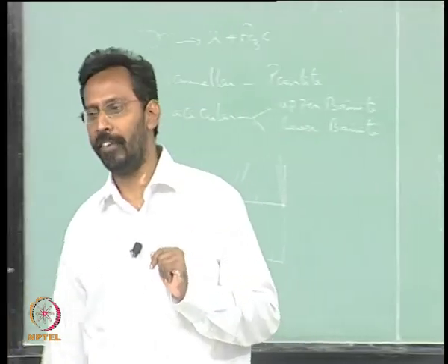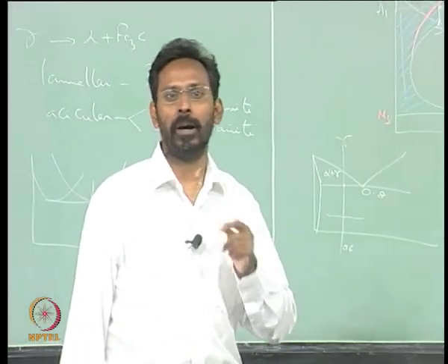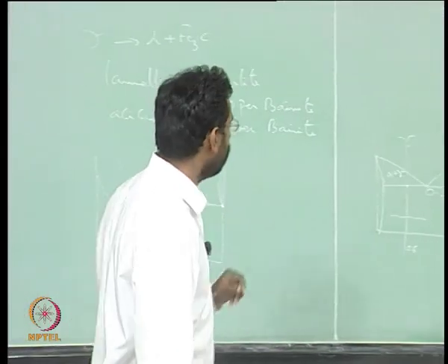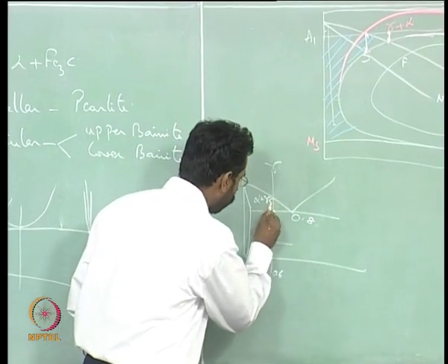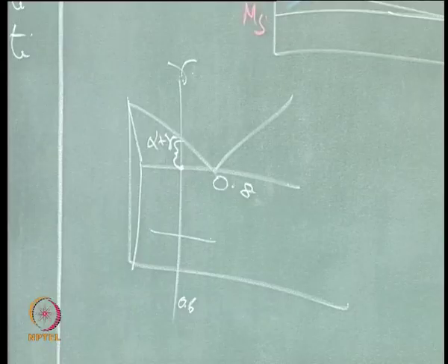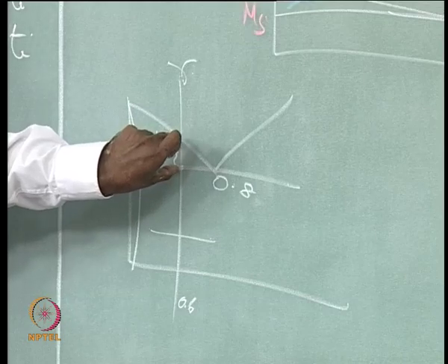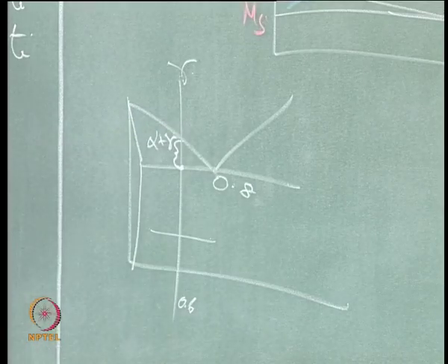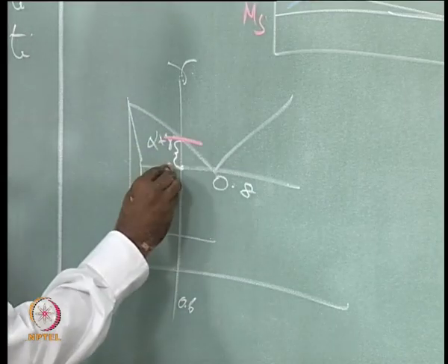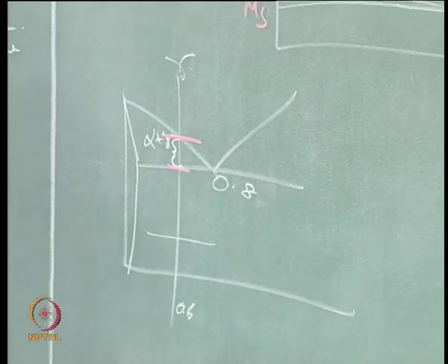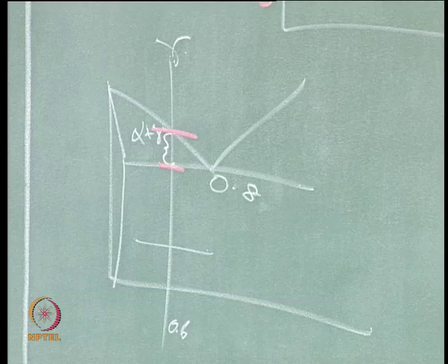The amount of hypoeutectoid phase is going to be smaller in a normalized case when compared to an annealed case. That means if I am cooling it faster, this particular temperature difference, what do we call that? There is a name given for that range, from here to here for a given steel. It is called the intercritical range, because these are the two critical temperatures.